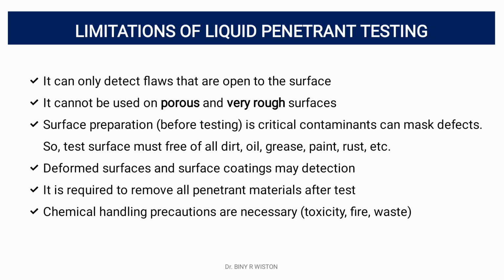Material compatibility. Not all materials are suitable for LPT. Highly porous materials or those that react to the penetrant may yield unreliable results. Compatibility testing is essential before conducting LPT on new materials.